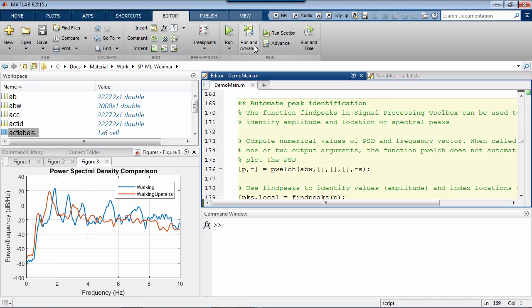To validate these, I'll also show you the spectrum for walking on top of the one for walking upstairs in a range between 0 and 10 Hz. Here, walking upstairs produces slower and smoother movements. Because they're slower, these peaks are all pushed to the left, and the smoothness in the time domain causes the peaks to the right of the fundamental to decrease very quickly, indicating softer time domain transitions. If this sounds unfamiliar, think about the spectrum of a pure and smooth sine wave, which has a single peak in its spectrum, compared to that of a square wave, which is full of high-frequency harmonics.